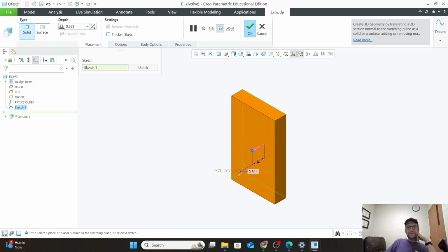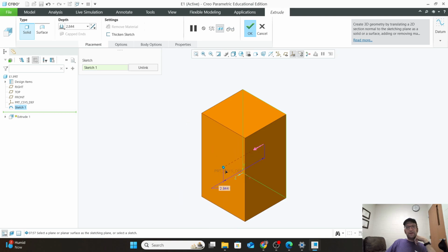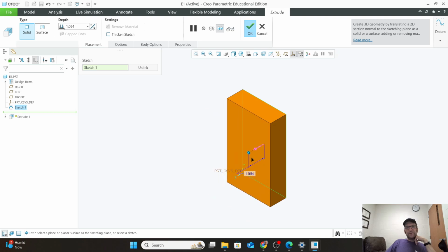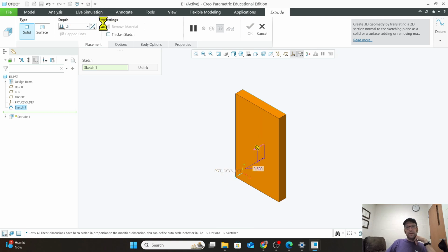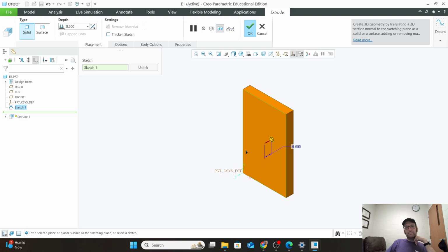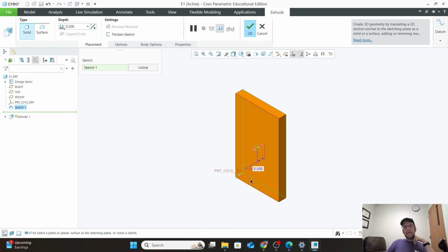We can grab this yellow dot and stretch it out and do the inaccurate thing. When we're at 3 decimal places, it gets to be a little bit harder to lock and knock right down and get right on that 0.5 inches. So we can either come up here and set that depth to 0.5, or I can come right here and type that in and hit enter there.